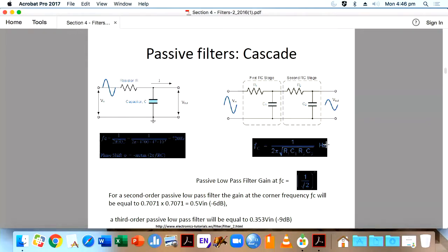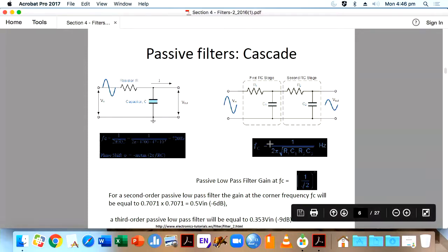R2 C2 hertz. So you have to take into account, it is very difficult to match R1 equal to R2, difficult to match C1 equal to C2 exactly. And then that is a cutoff frequency. And then there is an attenuation. Your attenuation is equal to 1 by root 2 the whole raised to n.